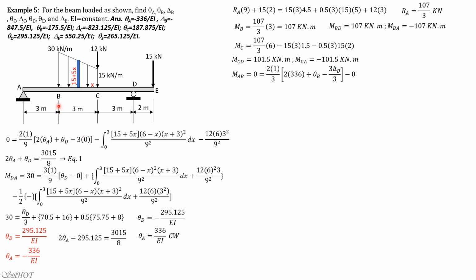Again, we imagine that B is below the original beam. It's here, so that the chord rotates clockwise again. So there's no issue with regard to our formula. It remained the same. So minus 3P, still 3 times P, which is delta B over L. Then because there's no load between A and B, the fixed moment will be 0. So from there, we can set up the first equation, which is theta B minus delta B equals negative 672. Call that equation 1.